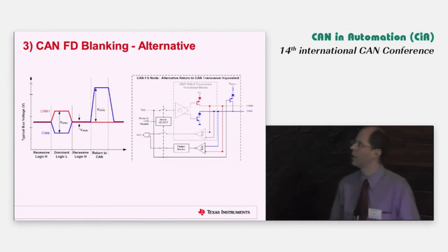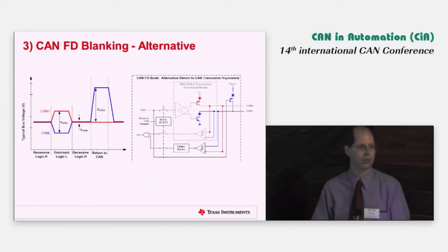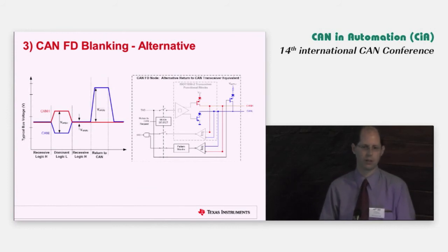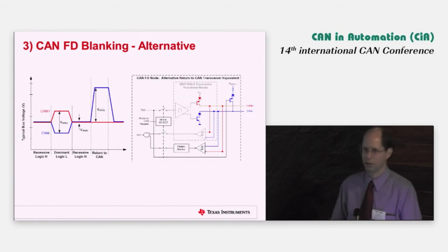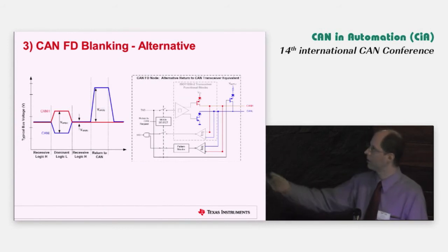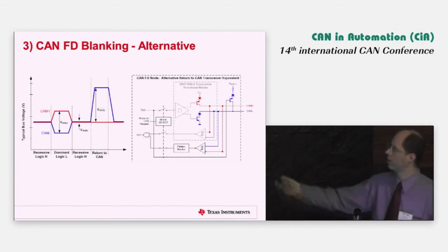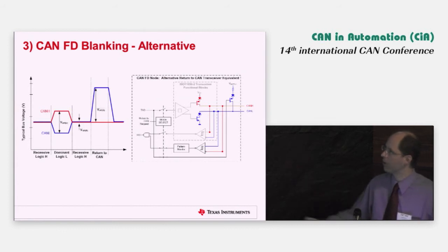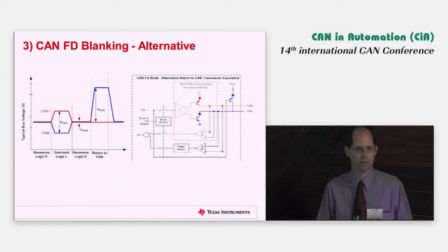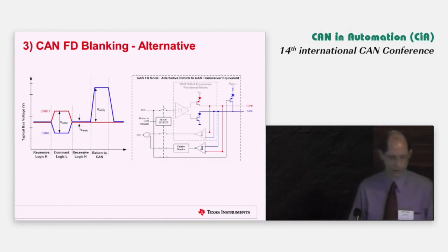This idea also has alternatives. Since we're not talking CAN bit times, we're only trying to get an inverted dominant onto the bus. We can generate that also from an alternative where we could simply pull a CAN line, CAN L, above CAN H through some single-ended type driver and get an alternative method to get an inverted differential signal onto the bus.